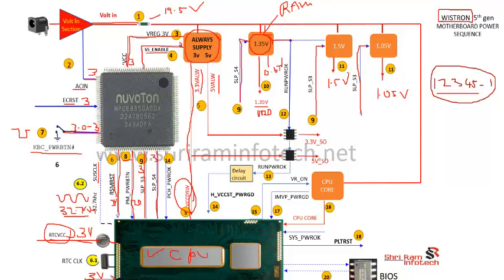And when all these voltages join together, they generate the power good like this, and all this power good is here, okay? And once this gets the power good, it's called the run power, okay? Once it gets that, this voltage will travel from here to here, then here to here, then 3.3 suspend and 5 volt suspend. The laptop comes on in the S0 state now, okay? So we have completed step number 12.